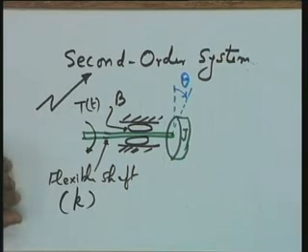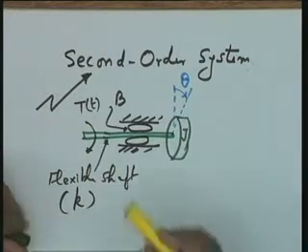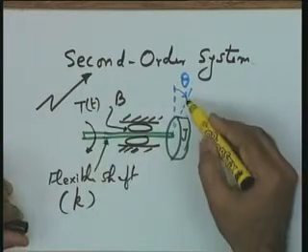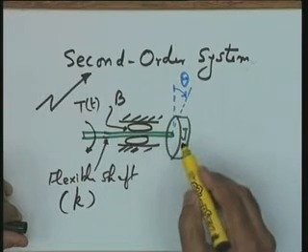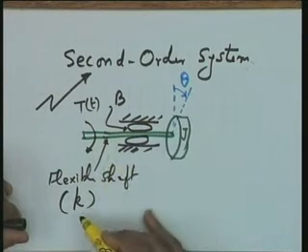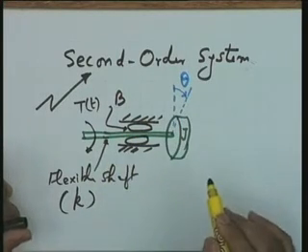Theta, that is the position, the twist of this particular shaft, is the attribute I am interested in. So, this becomes my output variable. So, input variable here, output variable, and the system parameters which are the constant parameters are J, b and k. You will note a change here please.